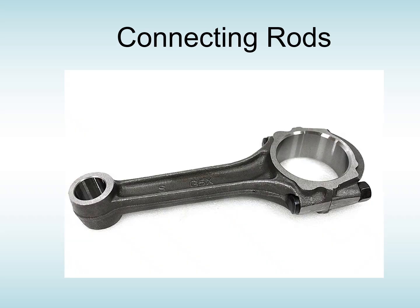We move on to connecting rods, but the only thing you really need to be careful of on these is match marks. When you're putting it back together, they need to be together, because otherwise, when that was machined, it was machined that way. If they were flipped at the bottom, it wouldn't necessarily be a round circle.